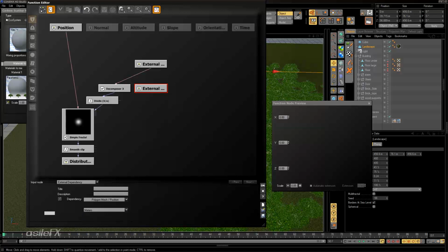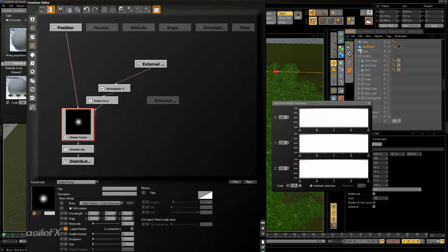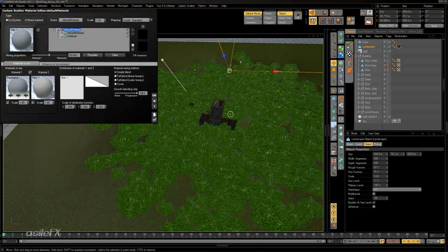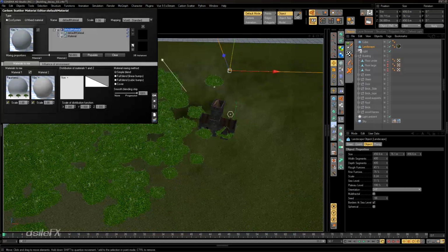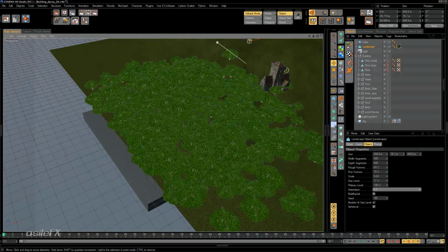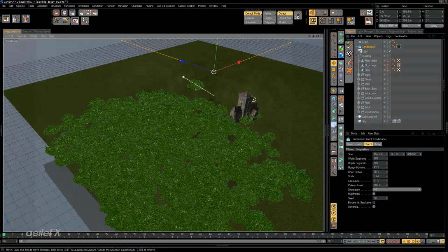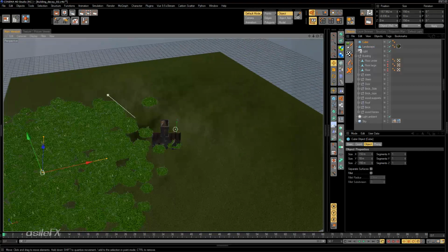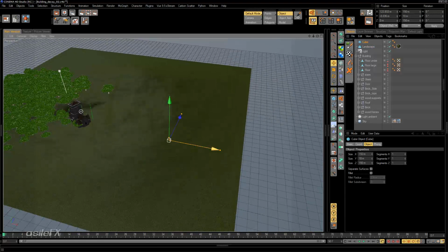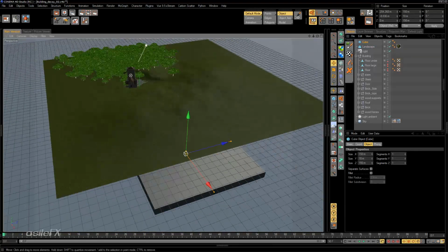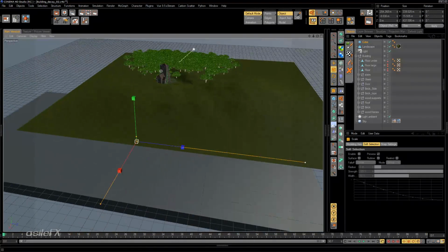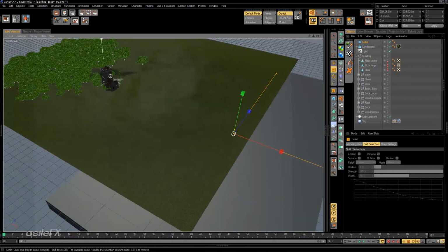We'll go ahead and try meters for the position. We might need to change it. And what we want to do is modify the origin to be connected to that. And it looks like that is working properly. So for the scale, it can be a little bit different than the way the position works. Position works better with the meters, and then the scale is working better with the centimeter mode. So I'm going to go ahead and stretch this out a bit.